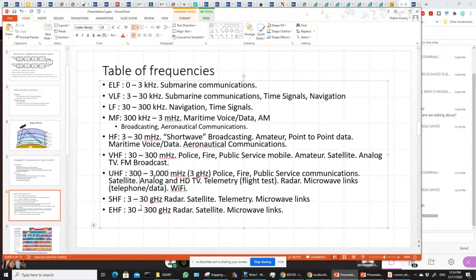But with improvements, particularly in multiple antenna technology, they're going to use 60 gigahertz now. So why isn't it going to disappear into the rain? Because they're going to use many different antennas, all working together. They couldn't do this in 2000 because the RF parts, not just the antenna itself but all the circuits that feed that antenna, are quite expensive. They had to have many of these in order to have one link that didn't go down. Each of those costs, like I said, maybe $1,000 to make, so it would make the whole circuit very expensive. So they had single antenna links, and these links just went out all the time.